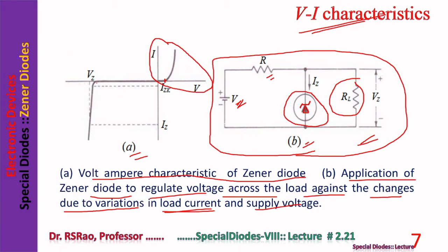voltage reaches a certain point called Vz. Actually, current starts increasing when voltage reaches a level we can call Vzk. Up to Vzk, current is insignificant, negligible. When voltage is Vzk, current starts rising. The rise is tremendous. That is the point one has to understand. A small increase in voltage in the reverse direction causes a huge rise in its current.